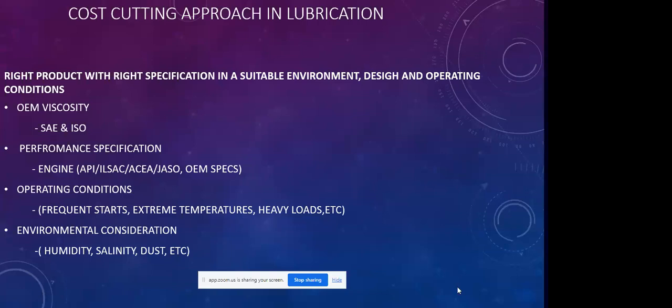So if your vehicle specifies a 5W40 or a 10W40 or a 15W40, that 15W40 is not enough. You need to know the performance rating of the engine oil. And here I've stated the S series. Oils that have SB specifications were designed for 1930 engine technology. So your vehicle comes with a 15W40 specification.